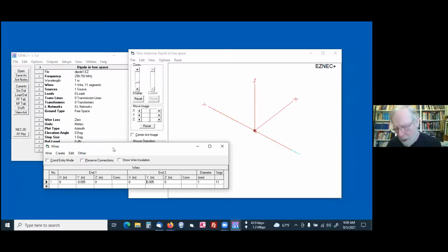And in order to conserve energy, we have to realize that if we want to have any gain larger than that, this spherical pattern will have to bulge out somewhere. And if it bulges out somewhere, it's got to bulge in somewhere. So we can't make an efficient antenna. It won't be possible to make an efficient antenna with a gain of less than 0 dBi, because if it had less gain, it would be poking in somewhere, then it's got to be poking out beyond 0 dBi some. I hope you're following that.